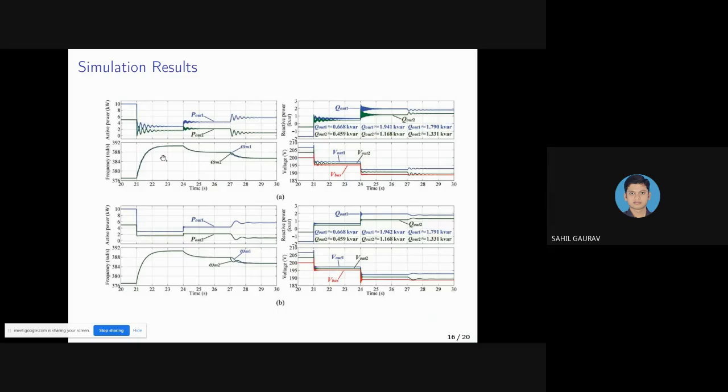And this is omega 1, omega reference, omega m, the angular frequency set by the inverter control. And for the reactive power, we can see how the oscillation has been damped out. In the second case, we get the same diagram for the reactive power, but with the oscillations properly damped out.